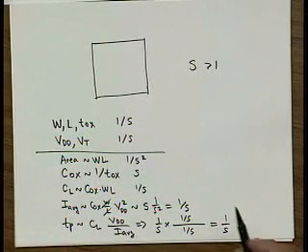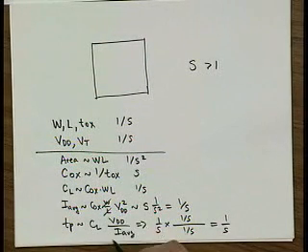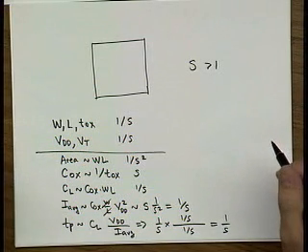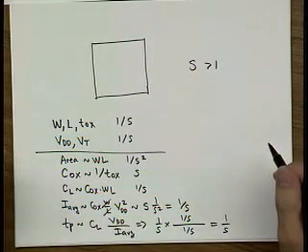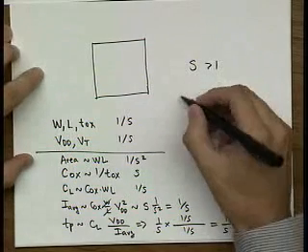Now, very important observation here. The improvement in propagation delay only came because of improvement in load capacitance, right? Your equivalent resistance was constant. So the only reason why you had faster transistors is because your capacitance reduced. Now let's look at the other factors.